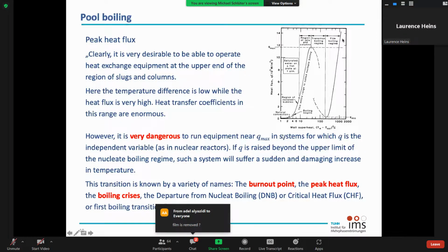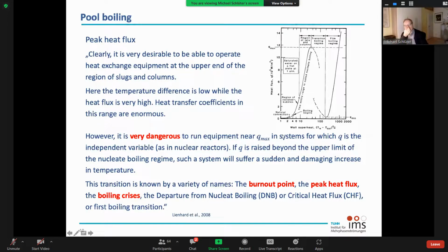Well, I would guess it is because the air, or the gas, the vapor, also transfers some heat. And of course, it also transfers more heat as the temperature gradient increases. And at some point, we would also have a big heat transfer, but that is just by vapor, probably. Yeah, so you mentioned it's conduction, right? Conduction through the vapor film, because in the film there is almost no strong convection, so more or less conduction. Yeah, thank you. This is true.